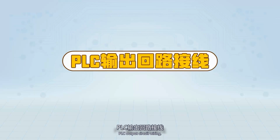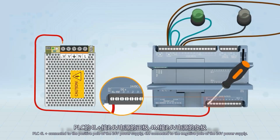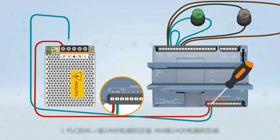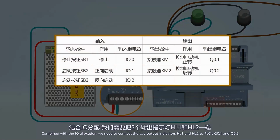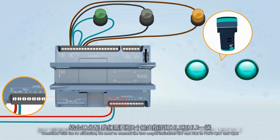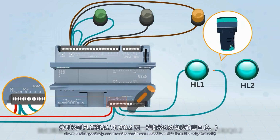PLC output circuit wiring. PLC 4L+ is connected to the positive pole of the 24V power supply, and 4M is connected to the negative pole of the 24V power supply. Combined with the I/O allocation, we need to connect the two output indicators HL1 and HL2 to PLC's Q0.1 and Q0.2 at one end respectively, and the other end is connected to 4M to form the output circuit.